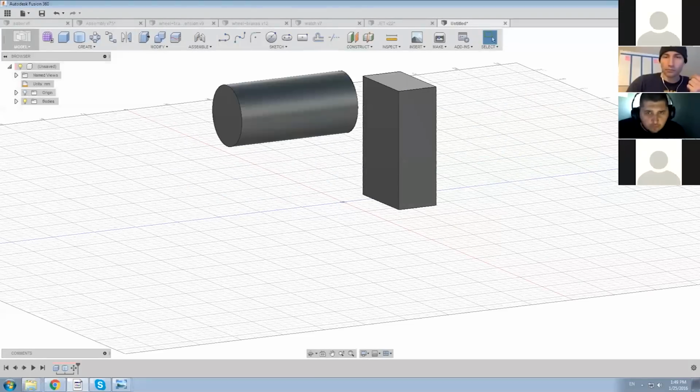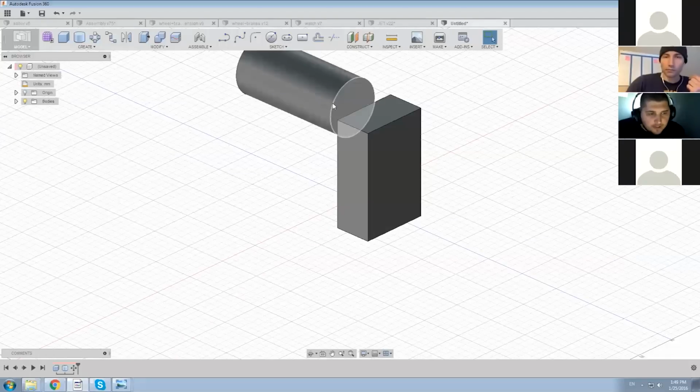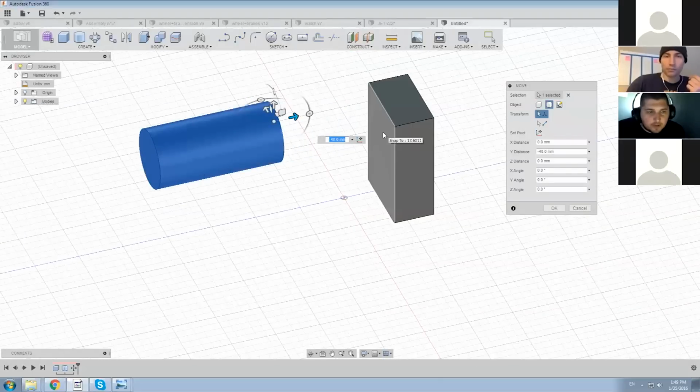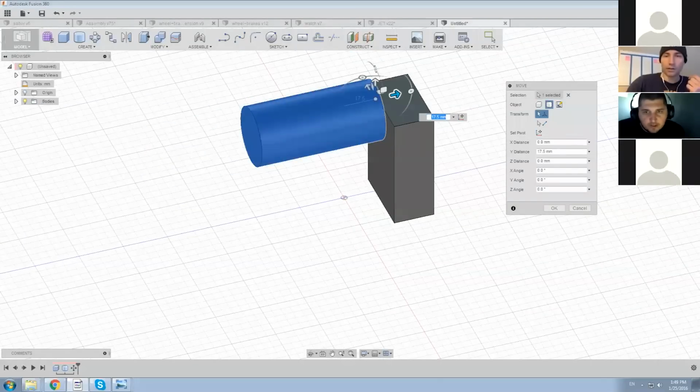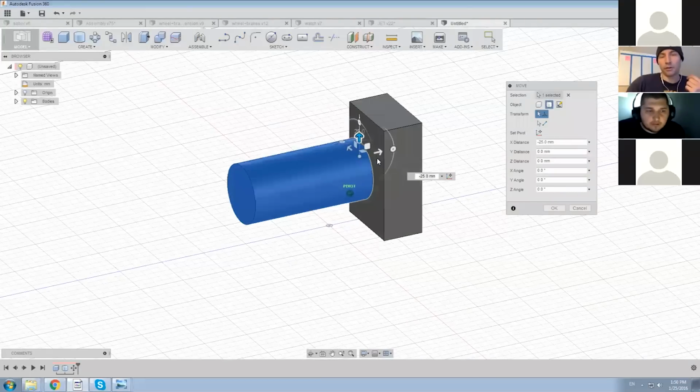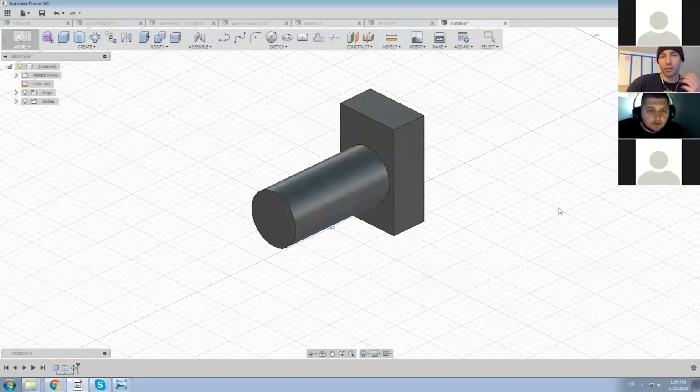It actually starts with me moving from the face that I want to snap, and then pointing it to the face that I want to snap to, and it does snap. So if that was an imported piece of geometry, that cube there, would it also function in the same way, where it would snap to that surface? No, because it needs to be recognized as a solid body.